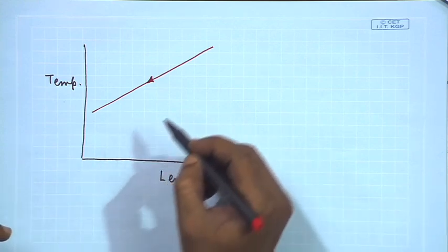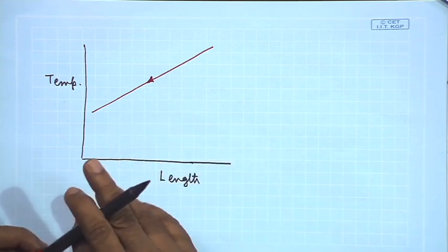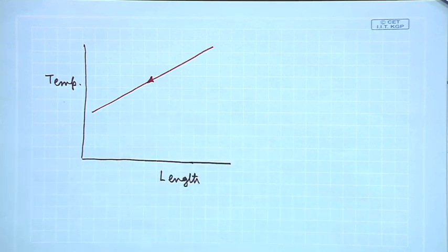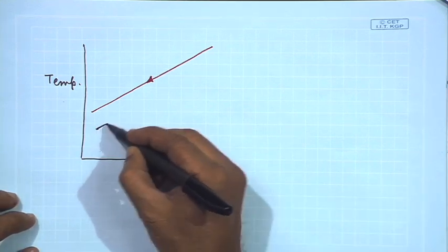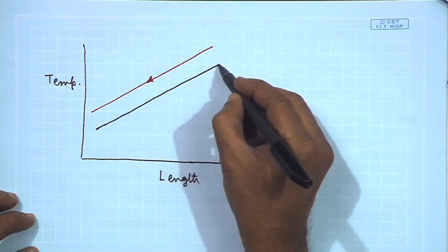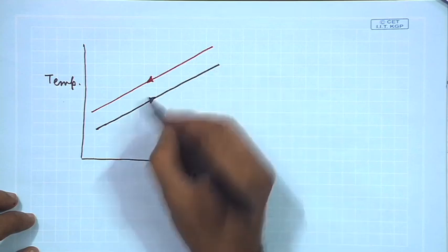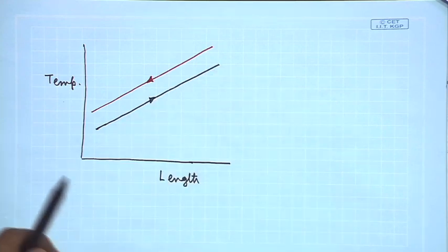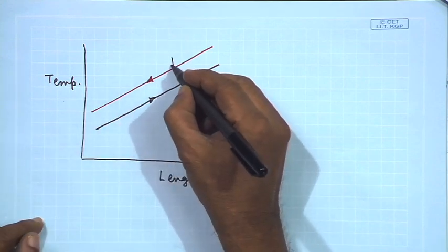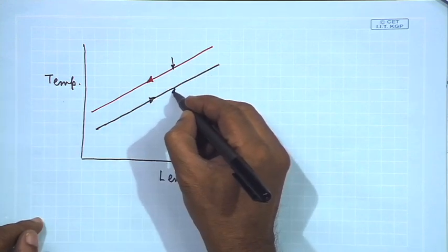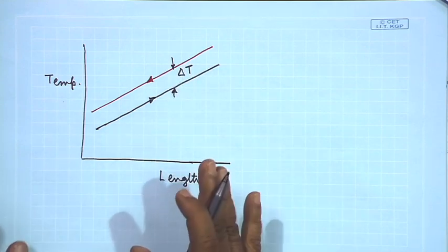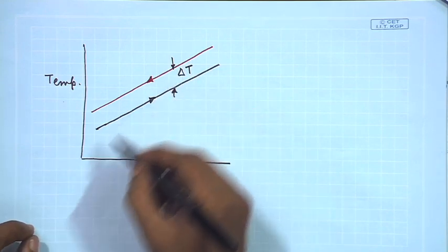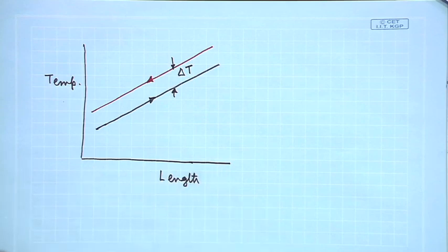If it is ideally a counter current type of heat exchanger, and HRSG is a counter current type of heat exchanger, the cold fluid stream could have gained its temperature like this. This could have been ideal, and for good heat exchange, one could have kept this delta T uniform along the length as far as practicable.